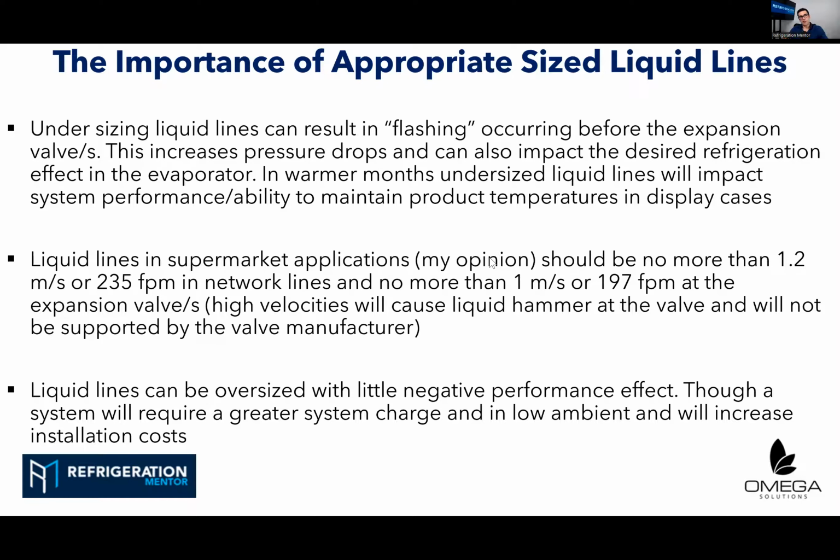Having too big of a liquid line would mean you need more refrigerant, but are there any other cases with velocity, that if you get that liquid line too big, your velocity drops off too much? So there is a potential there, Trevor, if we're talking significantly bigger, where we might have to increase the system pressure, so inadvertently run a system inefficiently.